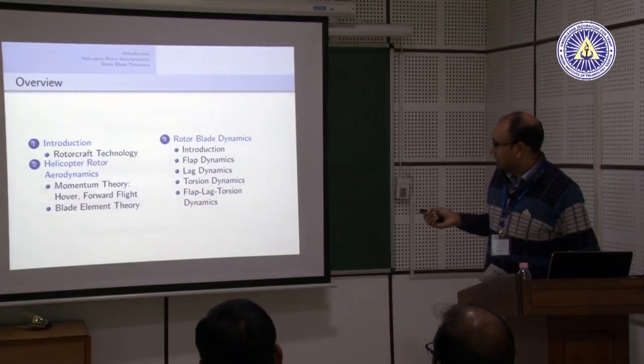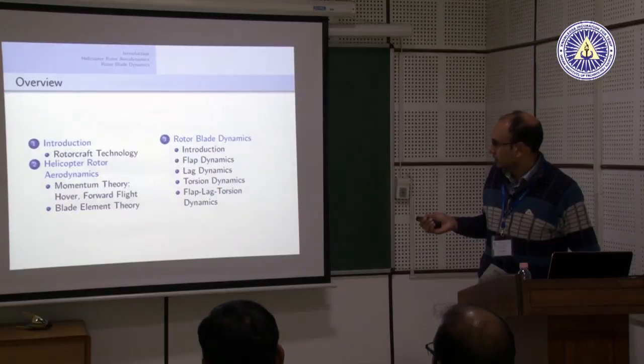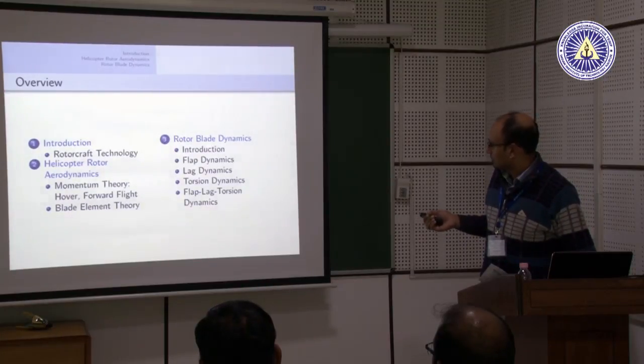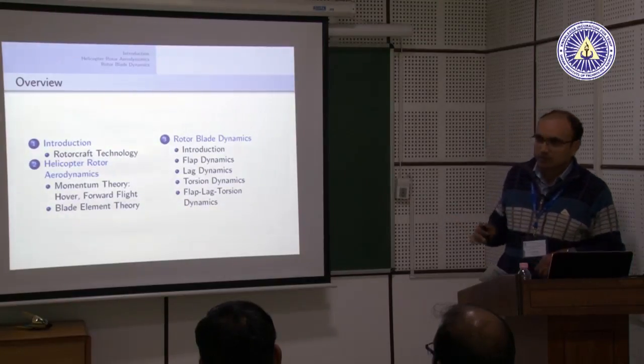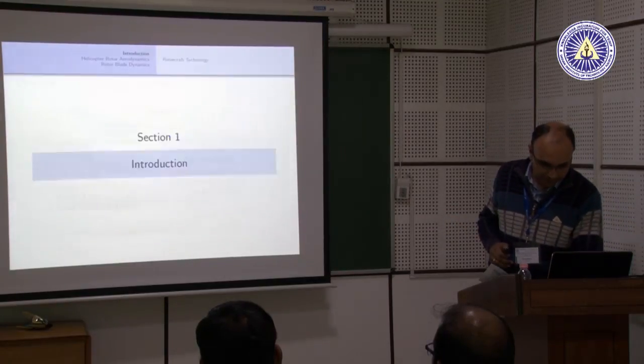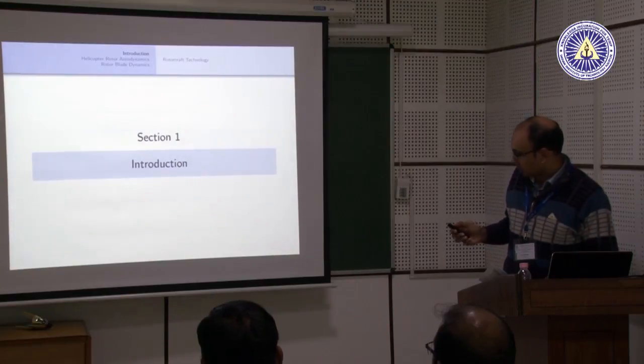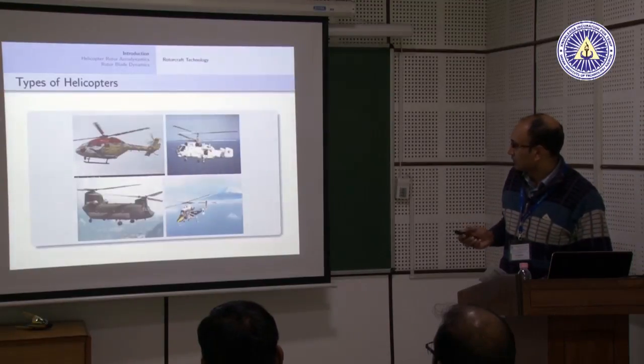Then we will go into the dynamics part. So aerodynamics is fine. Then we will talk about blade dynamics. I will introduce what I mean by blade dynamics. We will look at something called flap dynamics, lag dynamics, torsion dynamics, and then the coupled system. So this is more or less the recipe for today. Starting with the introduction about rotorcraft technology.